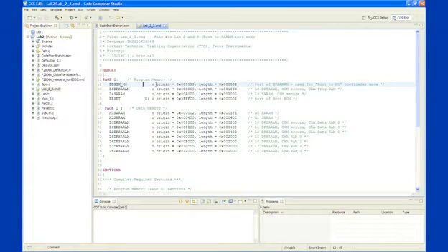So since this block is running a length of 2, the block M0 SARAM starts at 2 now, and we needed to take 2 off its length. The length originally was 400, so now it's going to be 3FE. This avoids an overlap with the next block of memory, which would have been M1.